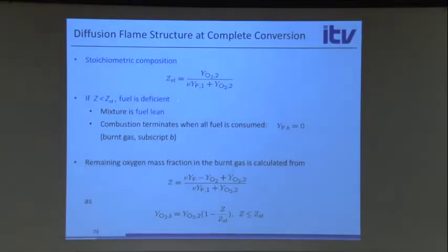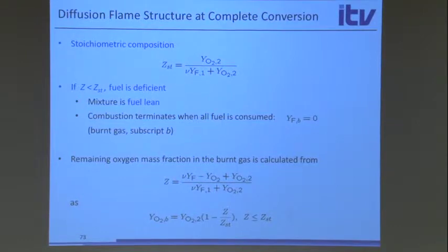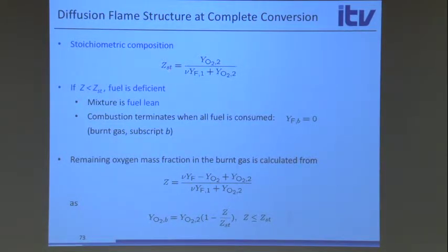So in the unburnt case, but now I would ignite it, and then we can also see what the composition is. This is the stoichiometric mixture fraction. By the way, I didn't say anything about the values. The typical value for methane, the stoichiometric mixture fraction, is 0.05, 0.055 actually.